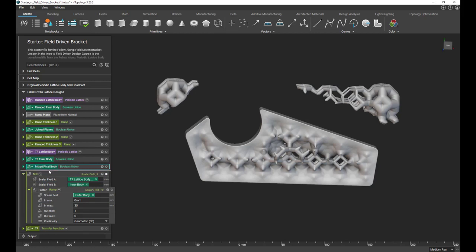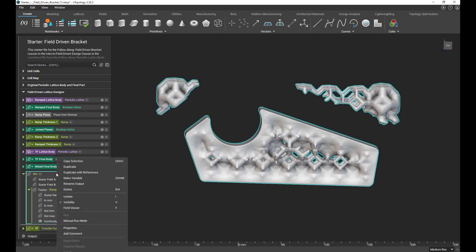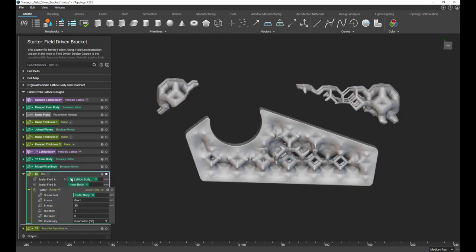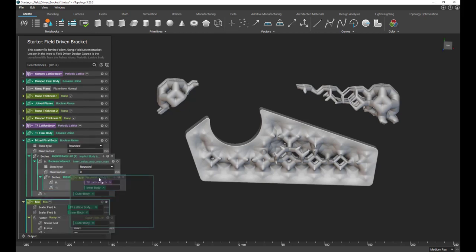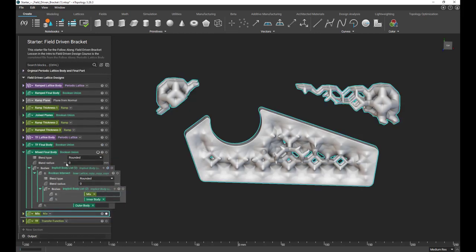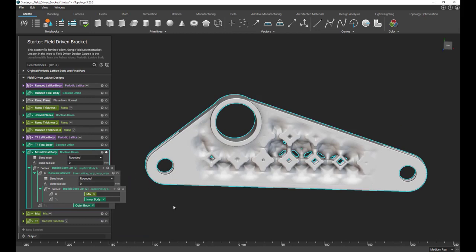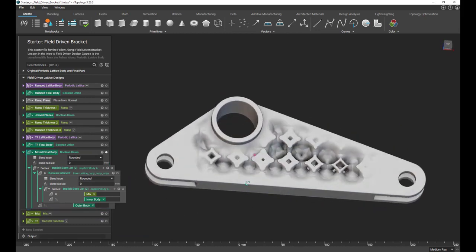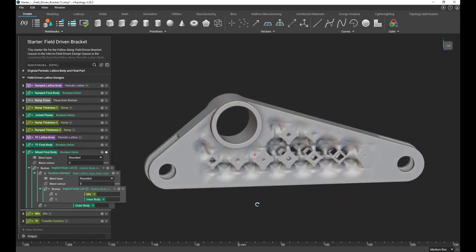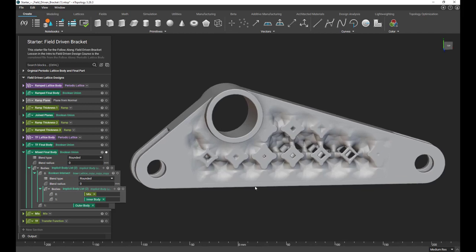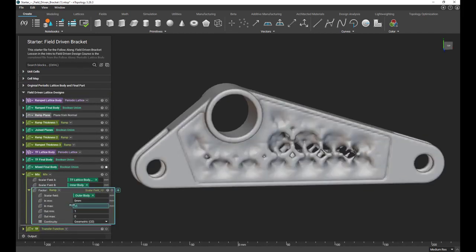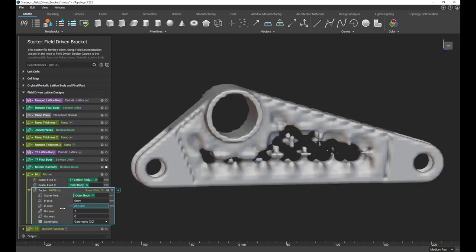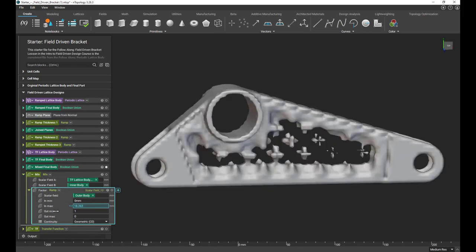Then we'll make this mix a variable called mix, bring it in instead of the lattice body to have our final mixed part. Using the arrow to the left of the input field, you can also play around with the different values for your nmin and nmax before deciding on a final value.